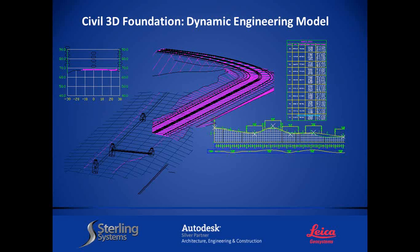Remember, this is tied to the existing ground through daylighting and slopes. You'll be able to see that. Also, your volume calculations, everything updates on the fly. As the alignment moves up and down, look for all my labels and how they automatically update, which makes sure my design and my drafting are synchronized.